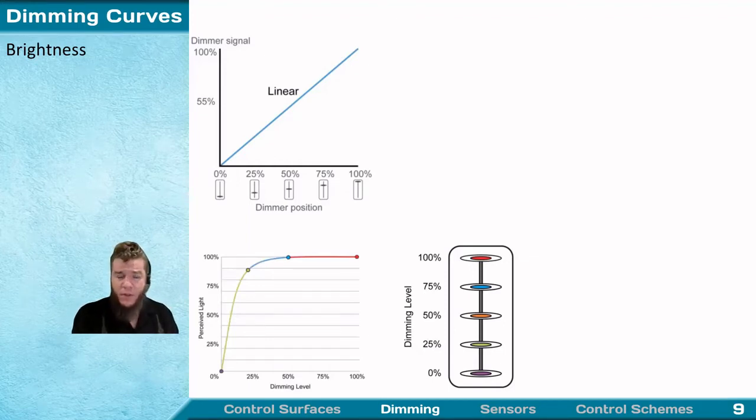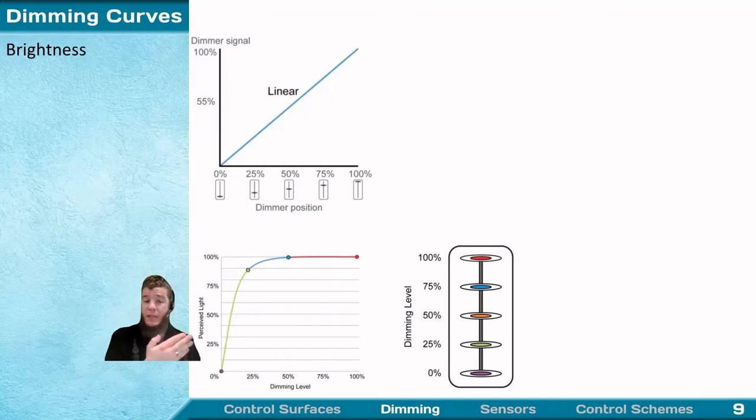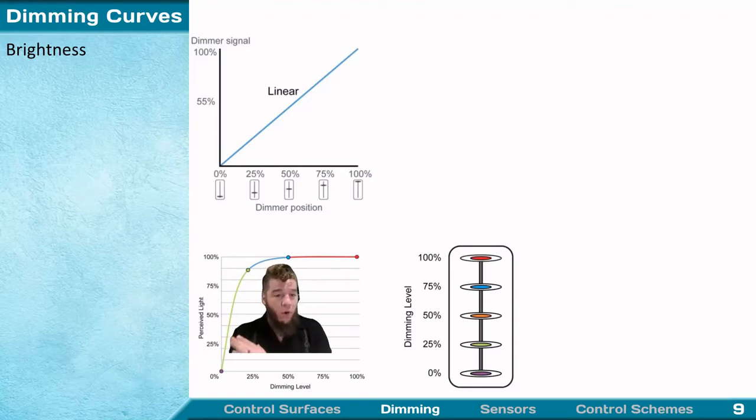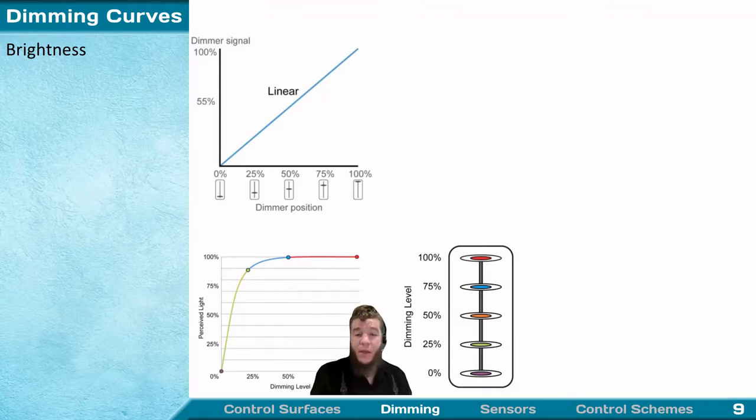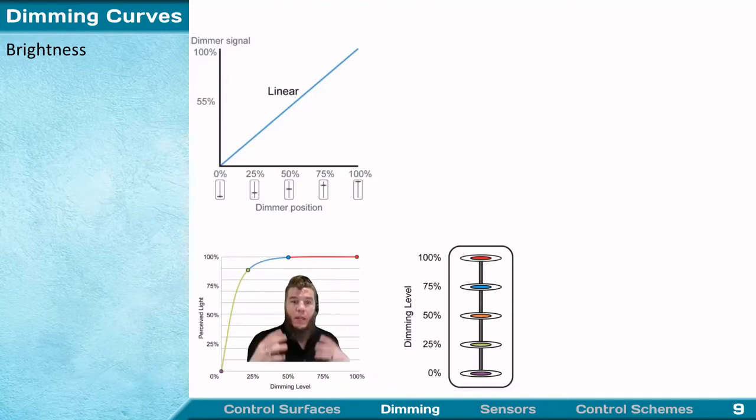That's weird. So here's a graph of the perceived light for that linear dimming approach. And what we see here is that almost all of the change is happening at the very bottom of that dimmer. In fact, between 0 and 25%. And if any of you remember the super old school iTunes, the original versions of iTunes, you would have the volume control on that, and all of the change would be happening right at the bottom. Like it'd be way too loud, way too loud, way too loud, and then off. Well, that's exactly what's happening here.